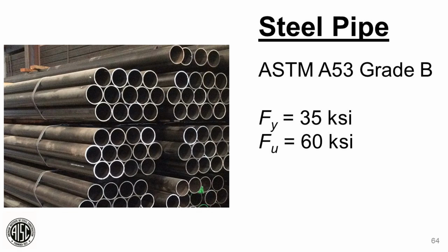To the best of my knowledge, all of the steel pipe sections, the diameters, the standard shapes, the extra strong, the double extra strong, should be readily available as A500 grade C material. So take advantage of that added strength.